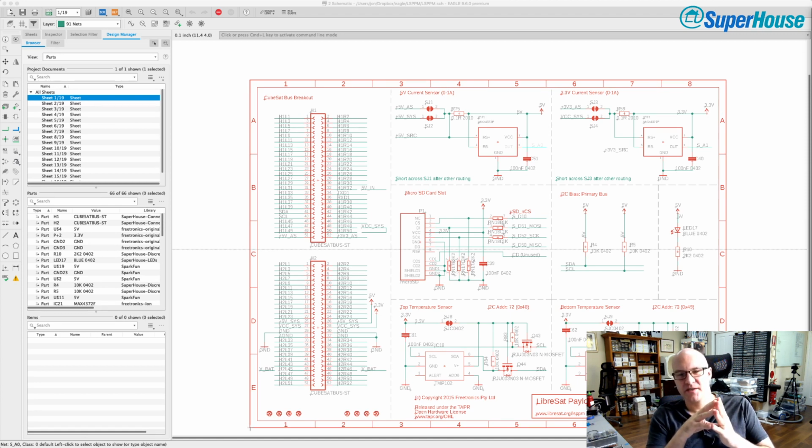But the way typical radios work is they have a tuned circuit at the front end. You have an antenna, and the signal comes down the antenna, and the antenna itself will be picking up everything, depending on things like the characteristics of the antenna and the wavelength. It will be more sensitive to certain frequencies and certain polarizations, but essentially at the end of the antenna you'll have just everything. That signal then has to go into a tuned circuit which will reject anything outside of a specific frequency range. You'll have a bandpass filter, and anything below a certain frequency it will cut off. Anything above a certain frequency it will cut off, and it will leave you with just the frequency you care about, and you can amplify that and do a whole lot of stuff in hardware. So the end result is a signal which is just the signal that you want, and everything else is rejected.